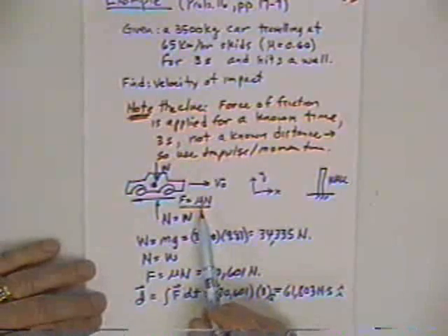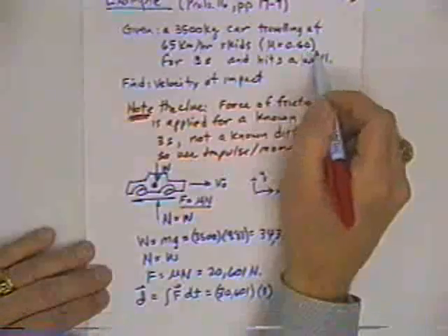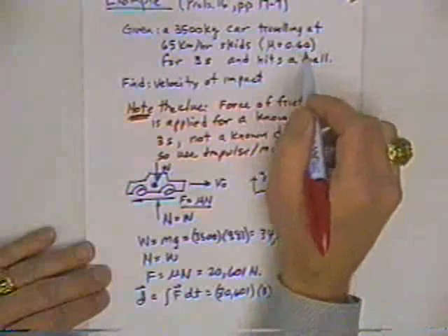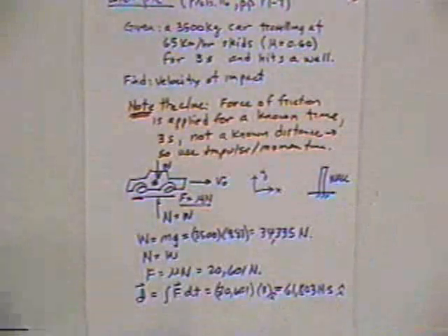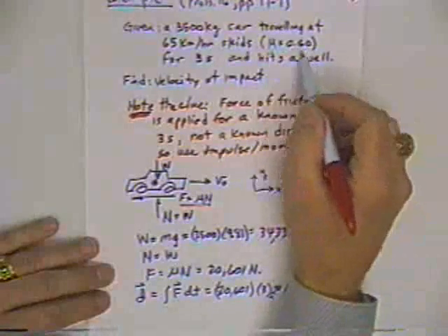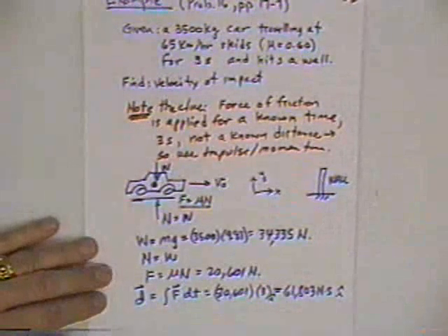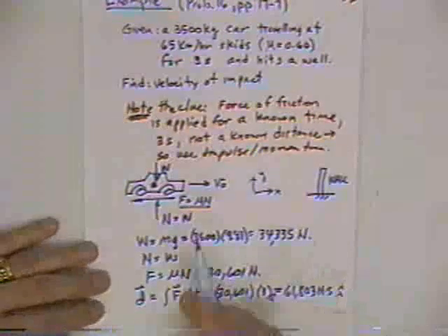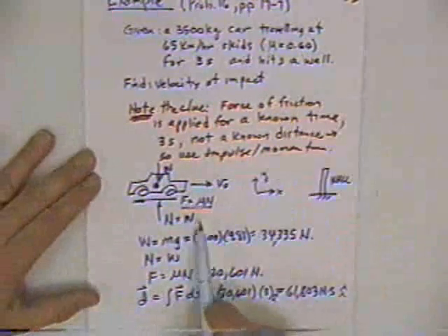Incidentally, good driving skill tells you that if you get on your brakes and you lock your wheels up, not only do you not have so much control of the car, but you don't have as good a braking action as you do if your wheels are still turning. That's because you're invoking the kinetic coefficient of friction as opposed to the static. Remember, the static coefficient of friction is a little higher. So if you operate your brakes in the optimal way, the wheels are still turning, they're not slipping, they're just at the verge of slipping, you can get frictional braking forces that are higher by the ratio of mu static to mu kinetic. So maybe you get 70% instead of 60% of your normal force on those wheels as braking action. And that's one reason you try not to lock your wheels up. That's why anti-skid brakes are, well, the more important reason is you have better control if your wheels aren't locked up, but you do have better braking action.